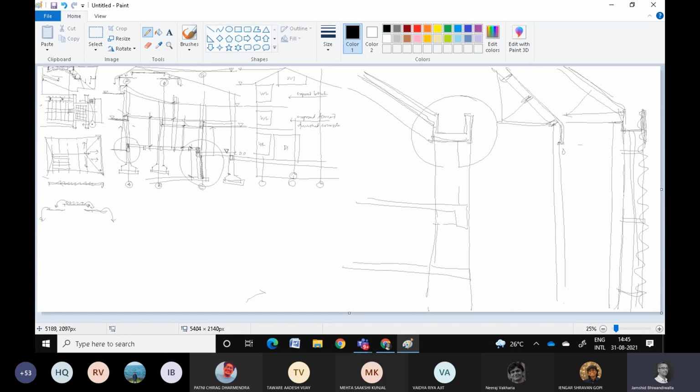Are you getting what I'm trying to say? Gutters are not pleasant to see along the edge of the roof, especially if you have long overhangs. If you have long overhangs, it makes sense to allow the water to fall off.